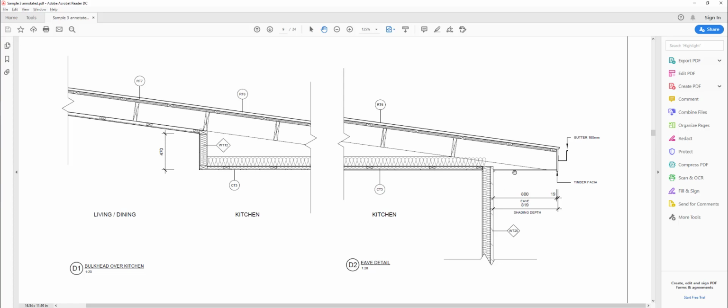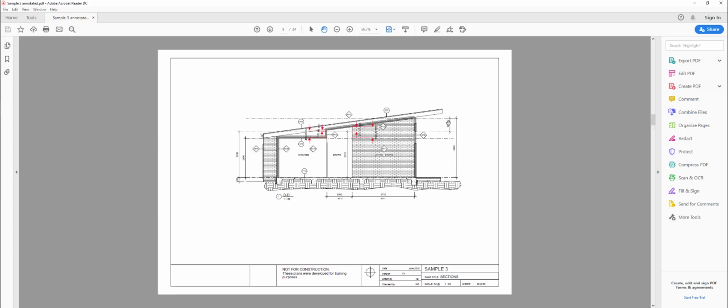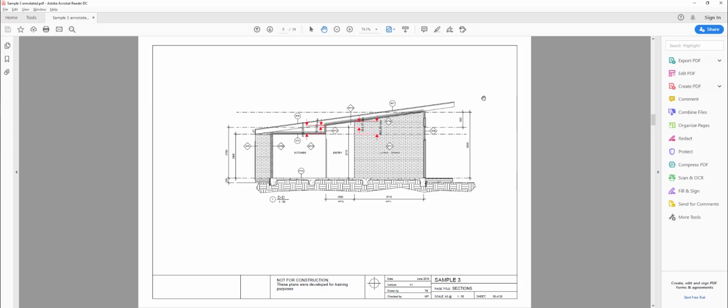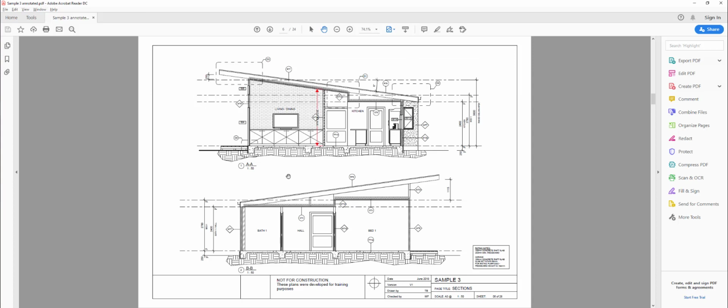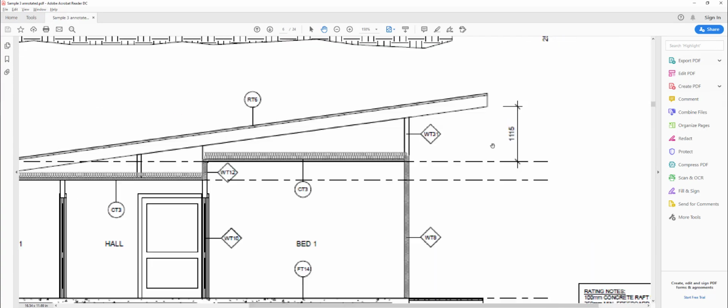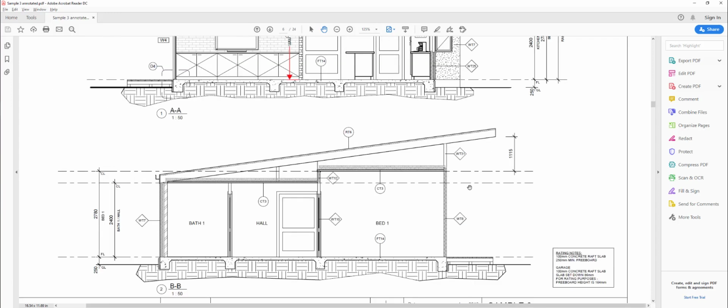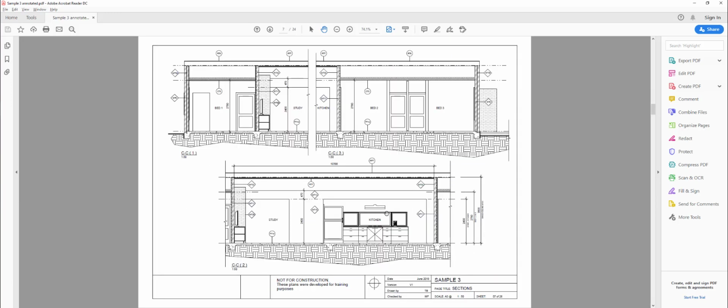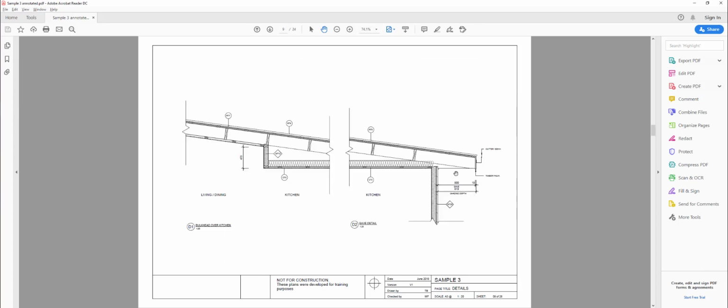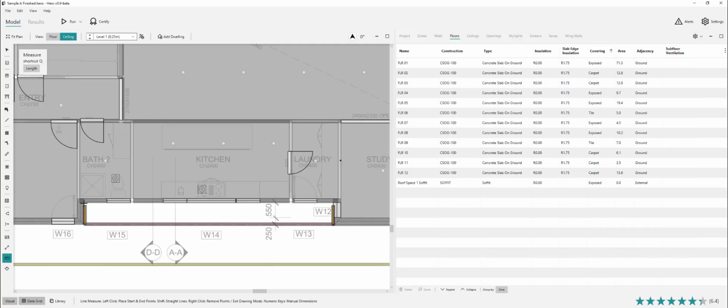From the northern end, the eave carrying through here on this pitched roof section would not be any style of soffit, and here again, this eave is the flat roof rafters, so we wouldn't consider there's any soffit here that's connected into this roof space shape. So we just have that southern area that we might want to model as an eave. We might want to just measure that area there so we can manually enter it.